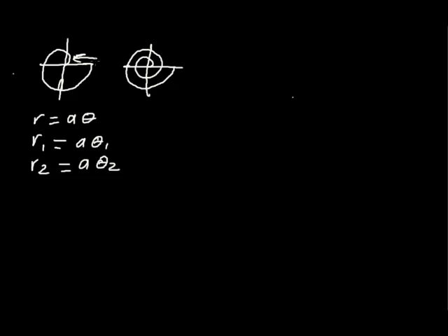Because you're not necessarily going to want to start at theta equals 0, because at theta equals 0, the radius of the cam is equal to 0, and you can't put any kind of shaft through a 0 radius, so that creates a problem for you. So you're going to start at perhaps over here. You have some non-zero radius, and then work your way out, and then you're going to end up stopping 2 pi radians away from that, which would be over here somewhere.